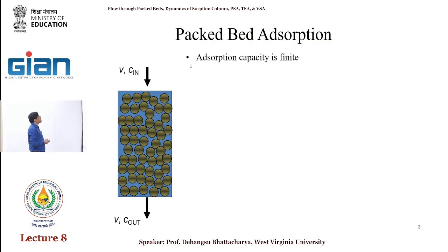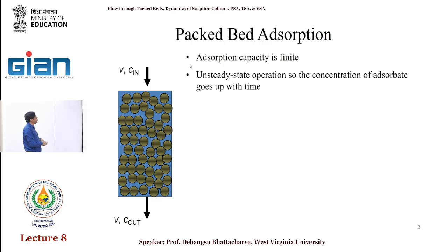The couple of things that you have to remember here is that for this packed bed, the adsorption capacity is finite, which I think will make sense, right? Because we have a maximum loading. So we say what is the maximum loading that we'll have here. Now, I keep saying this, that this is an unsteady state operation. So what would happen is that the concentration of the adsorbate goes up with time. So this will actually load first, then go here, then go here, then go here.